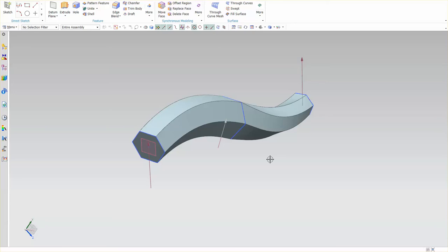Now, again, I simply used a spline. I put in planes at the end points and one at the center point. If I needed to have additional sections, I could dump additional datum planes in at those locations, and make sure I put a point in at that location so I can position the origin of my sketch to that location as well.